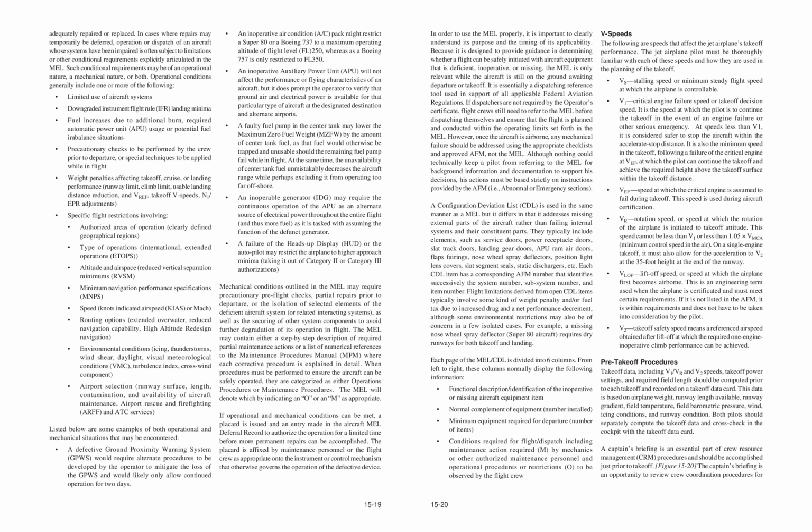Weight penalties affecting takeoff, cruise, or landing performance, runway limit, climb limit, usable landing distance reduction, and VREF, takeoff V speeds, and EPR adjustments. Specific flight restrictions involving authorized areas of operation, clearly defined geographical regions.